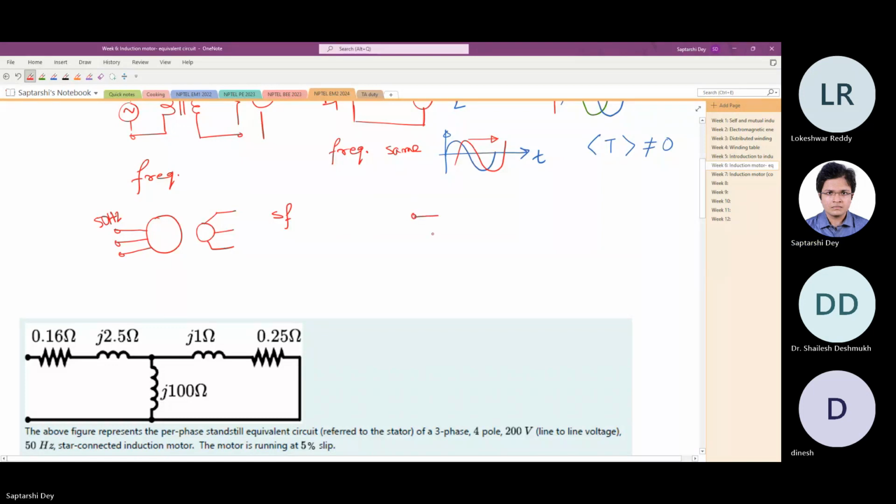So now, by some way, we have to connect the stator and the rotor circuits. So how does the rotor circuit actually look? It is like this, right? There are either windings or squirrel cage which are short circuited. So definitely it looks like this, short circuited RL circuit. And there is some induced voltage, E rotor, let us say.